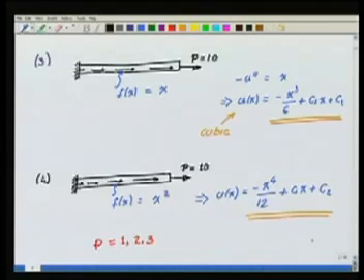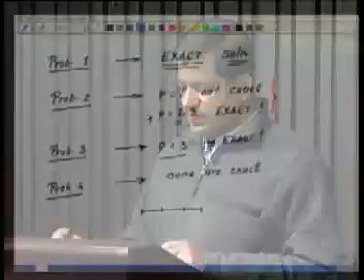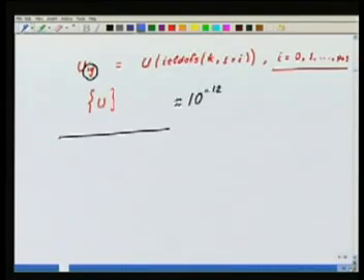I can certainly devise variants to these problems. One can play around with the boundary condition that one applies. So, imagine I can also do this, I can apply the spring boundary conditions, I can do various things to get the effect of the various boundary conditions, and for these various boundary conditions only these coefficients C1 and C2 are going to change. The nature of the solution is not going to change. So, I can play with all the boundary conditions that we have there and check whether my boundary conditions are being properly applied or not.